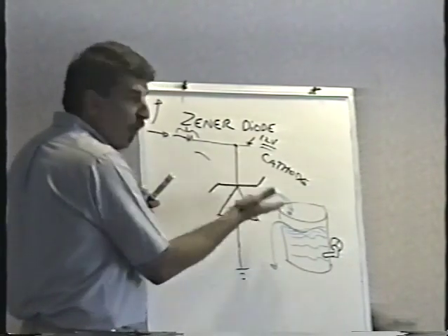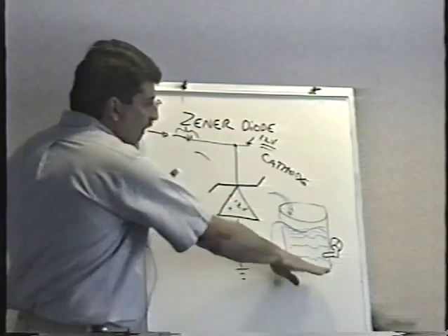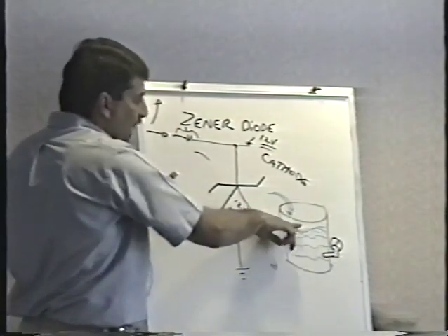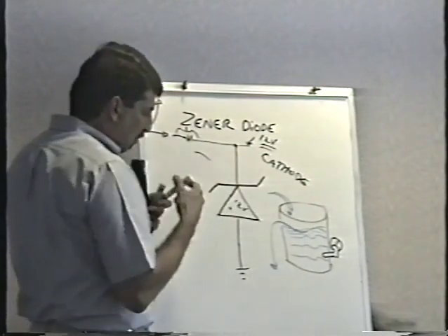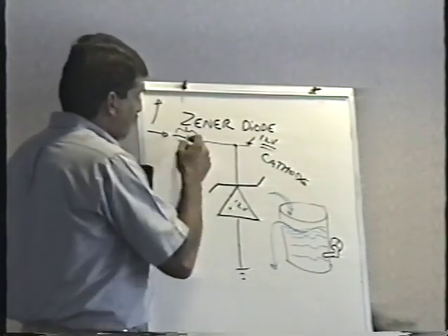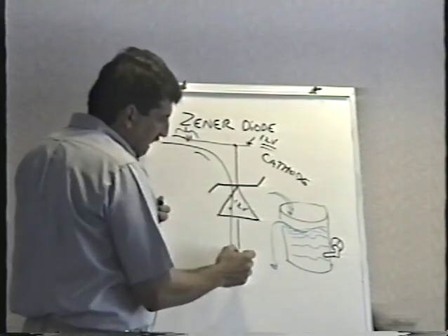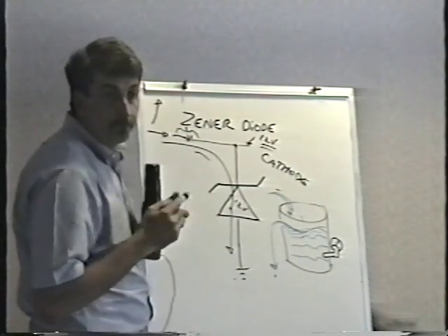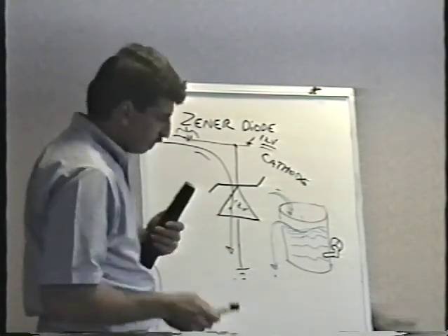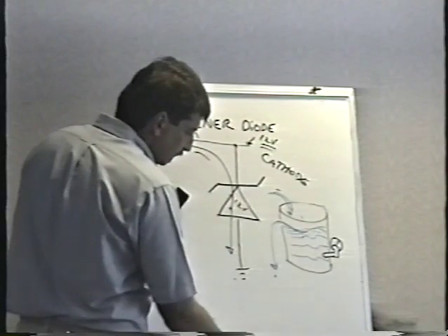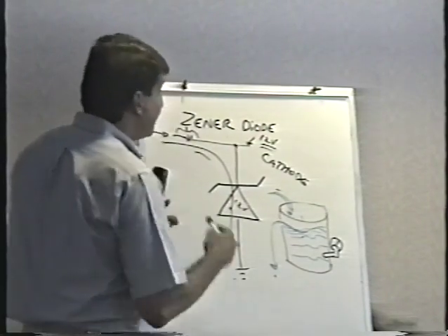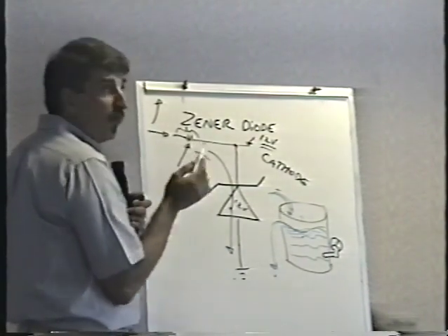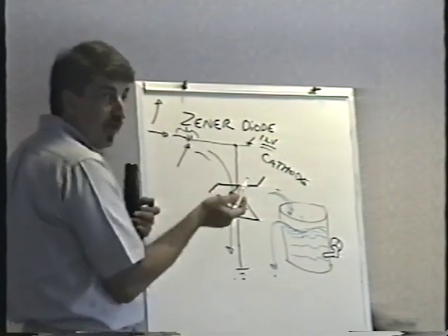Same thing here. I've got a hole here, 12 volts. Put in 1 volt, 2 volts, 3 volts, 4 volts, 5 volts. It continues to build up the pressure. When I get to 12 volts, if I try to put any more voltage on this thing, the extra voltage is going to go through the Zener diode to ground. It's going to come out and land on the ground. Same thing. Yeah? So is that safety feature good for unlimited voltage, or is it? It would be, yes, depending on the size of this resistor. There's always a resistor here, called a voltage dropping resistor, and I'm getting more advanced than I want to.